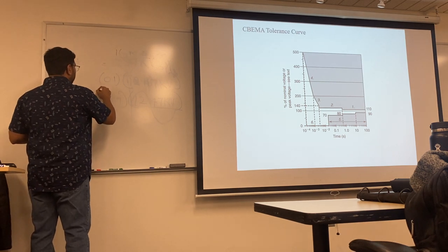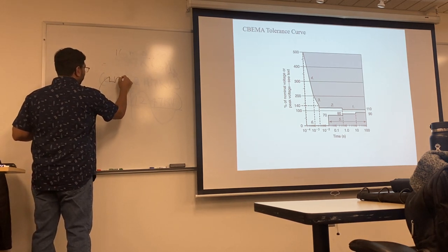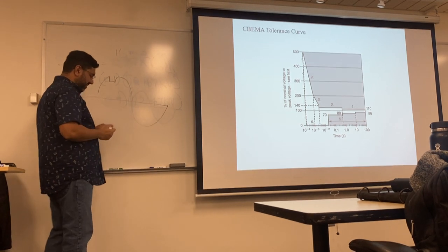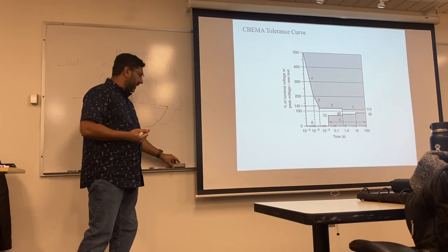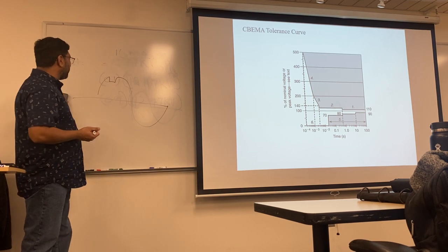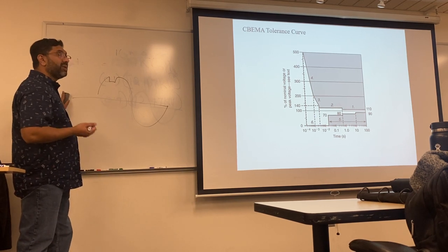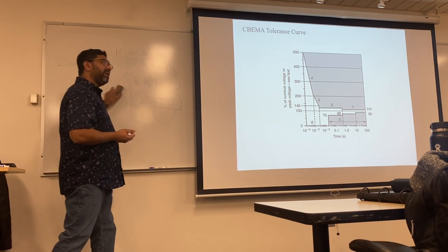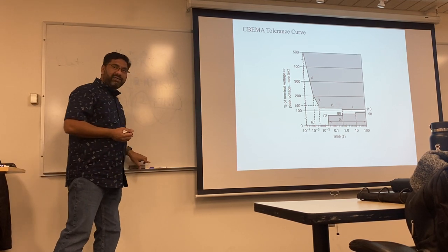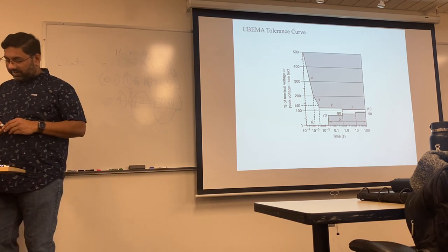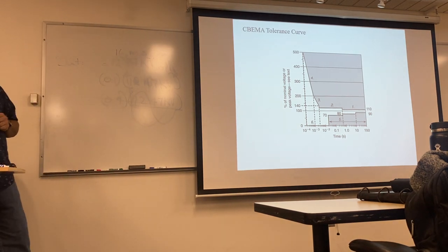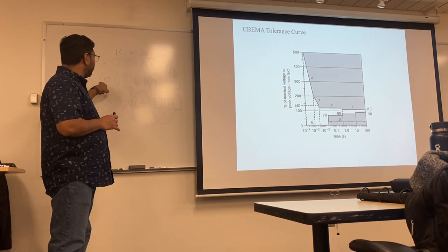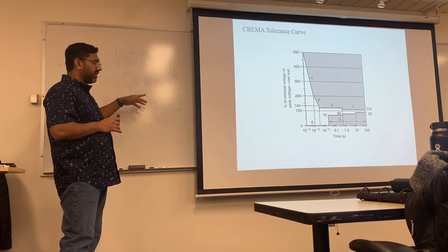Notching is like a pinching of a voltage. You have a sinusoid and then there is a dip. And noise would similarly be that from a sinusoidal point of view, it doesn't look like a sinusoid. Your entire lab 3 is going to be on that, where you don't see a sinusoid and you're getting frustrated, and you later learn that when you add a bunch of different sinusoids, the sine wave itself gets destroyed and it looks really weird.